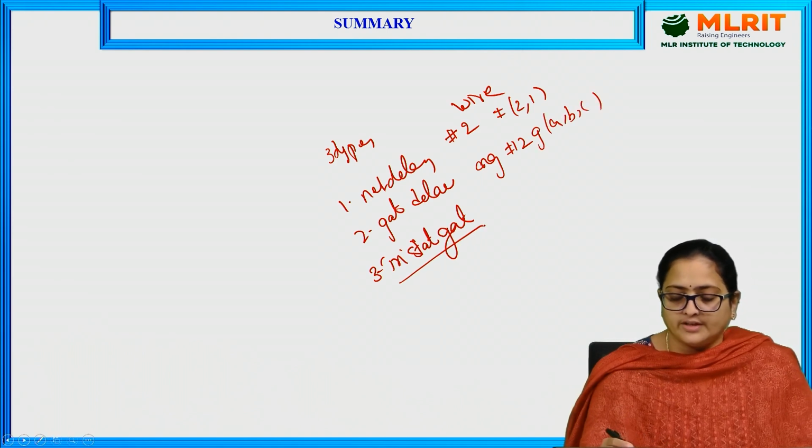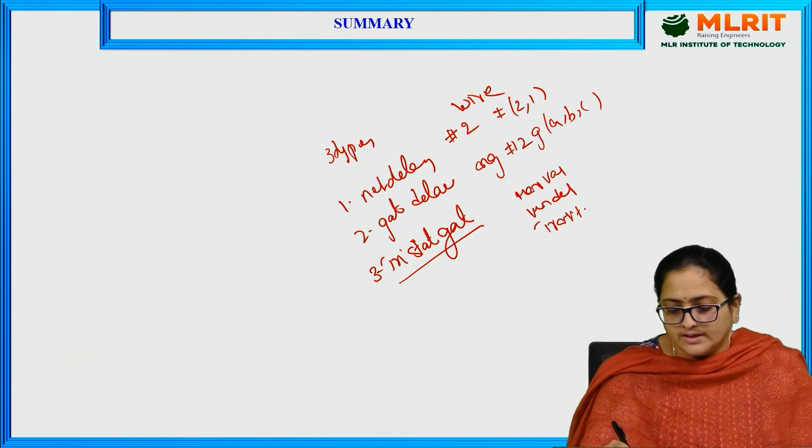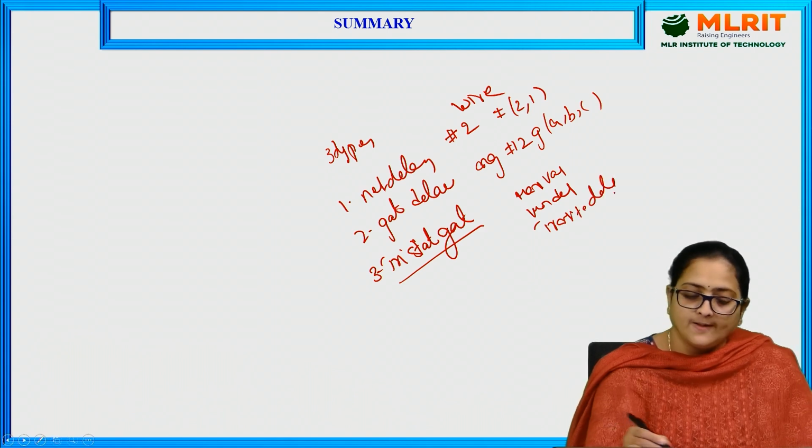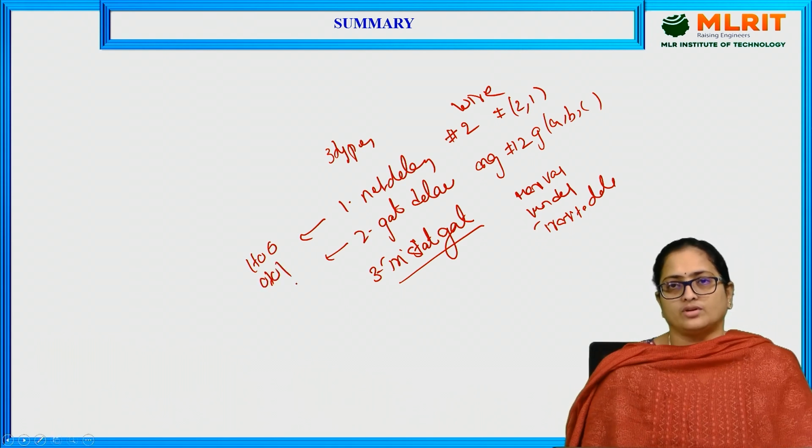And for tri-state gates, you can implement a maximum delay, minimum delay, as well as transient delays. Here and here you can implement for positive transition and also for negative transitions.